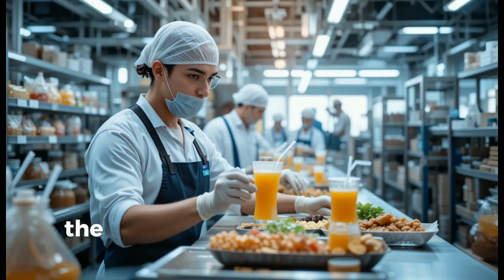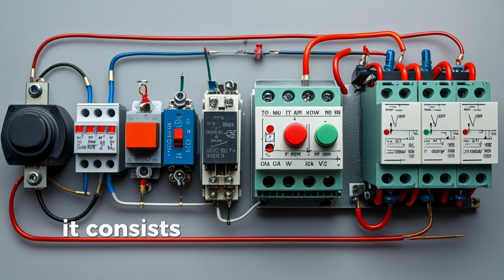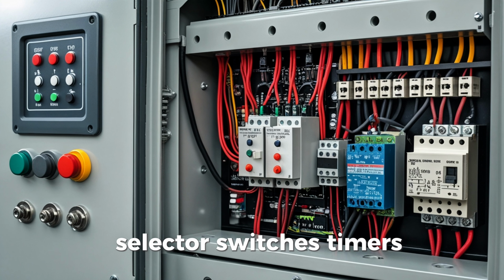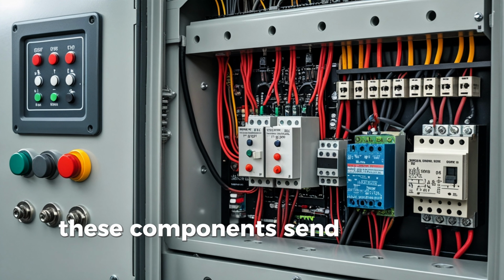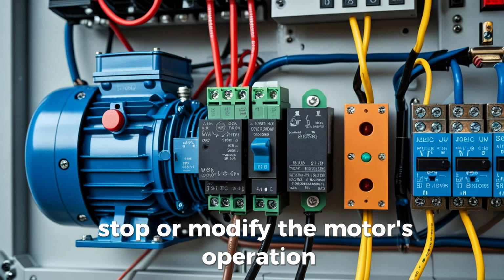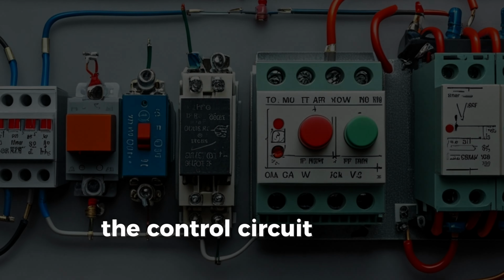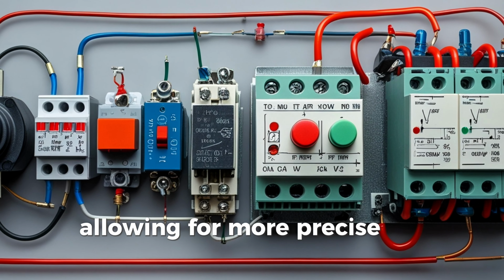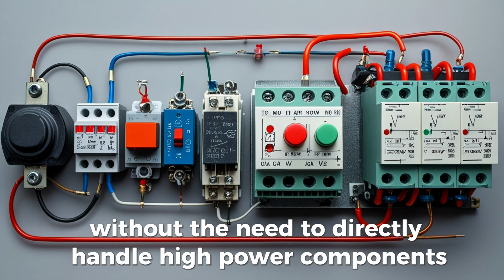On the other hand, the control circuit manages how and when the motor operates. It consists of low-voltage devices such as push buttons, selector switches, timers, relays, and auxiliary contacts. These components send signals to the power circuit to start, stop, or modify the motor's operation based on certain conditions or user input. The control circuit enables automation, interlocking, and protection features, allowing for more precise and reliable motor control without the need to directly handle high-power components.